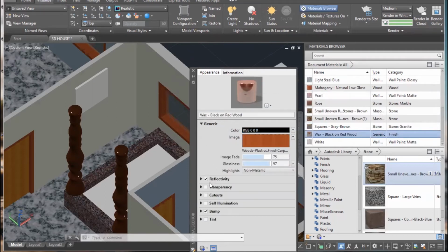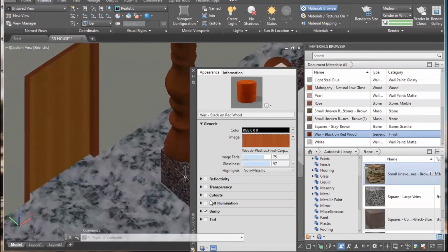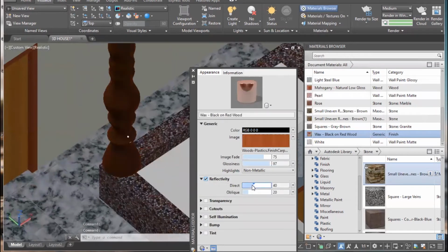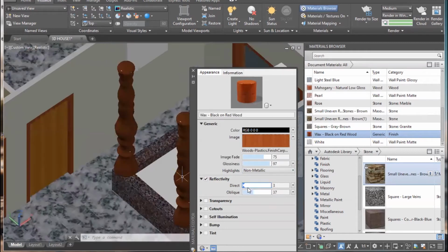Can you see there are some more properties here? Because the nature of this property is glossy, there is a reflection that comes over here. I can switch off the reflection. So no more reflections on it. Okay. And the bump mapping, the detailed texture, this one I told you about. I don't need any bump mapping, so I can make it flat like this. Or reflectivity, I need to make it less. Or I want to make it more opaque. I can increase this one, more opaque. Transparency can be adjusted on it. Direct to reduce, this one. So the nature can be adjusted from here.